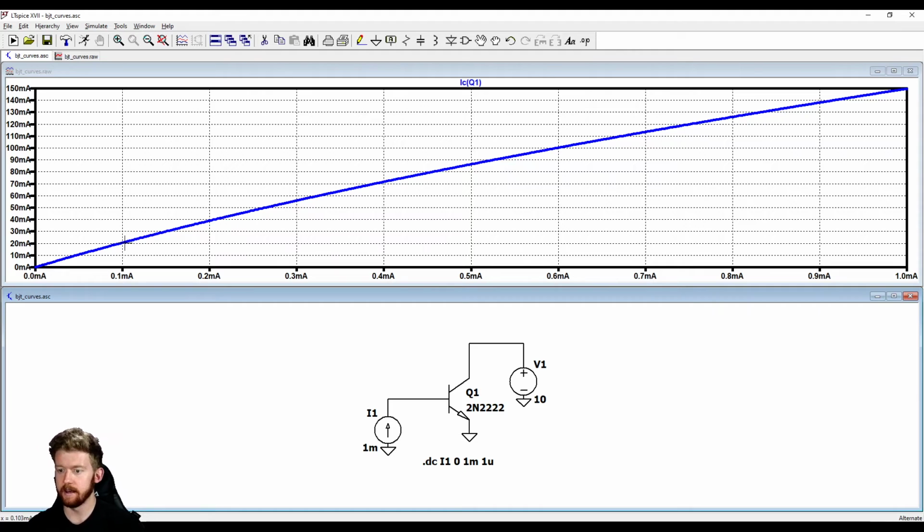That's something you have to take into account, that beta is going to change depending on where your operation point is. But usually whenever you're in the low current area, which is kind of what you want, we're going to have a pretty nice beta. So this looks almost linear. We can still tell it's not exactly linear, but it looks a whole lot better than it did previously.